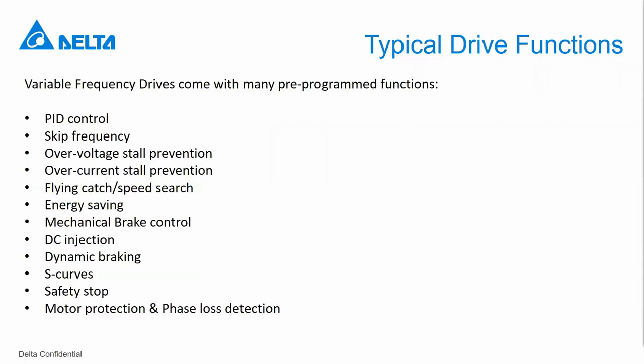There is one question still about that ramp direction. The question was: if I want a pressure of 6 bar, if below it ramps up and if above it ramps down, can I change it and operate it in another way? But normally, automatically with a PID and a pressure sensor, it will always go up and down around the 6 bar, what you have as set point.